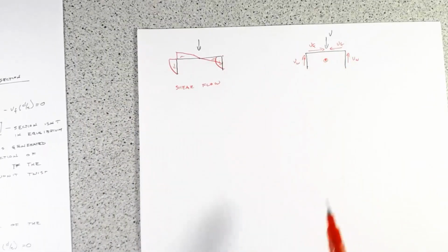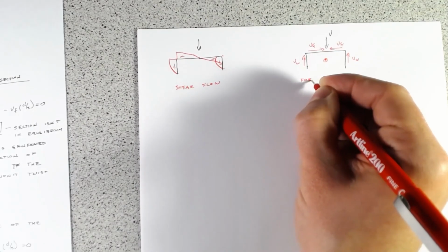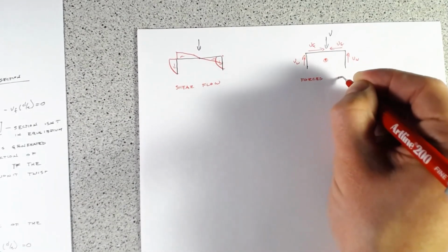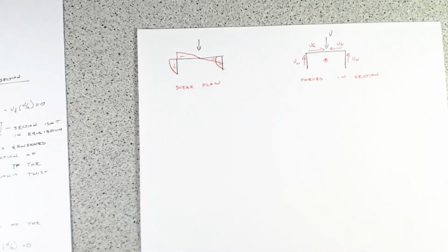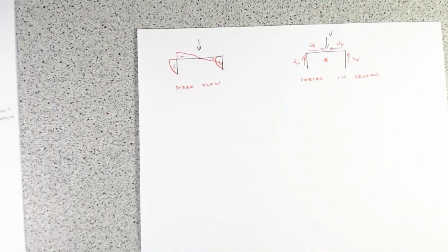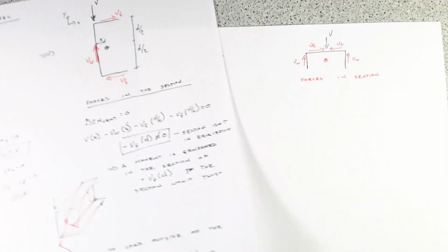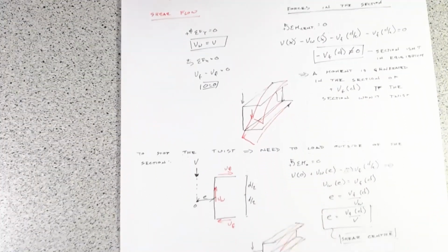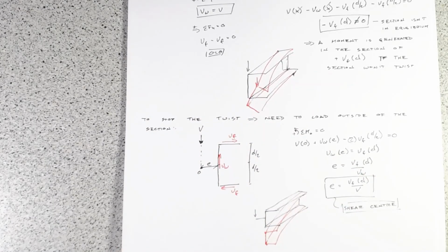It really comes down to what the distribution of these shear forces are, as to whether you're going to have a stability problem. So that's really the essence of why we teach shear flow for structural mechanics: this twisting action and determining if it's going to be a problem.